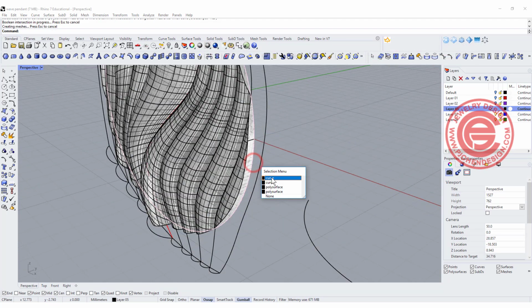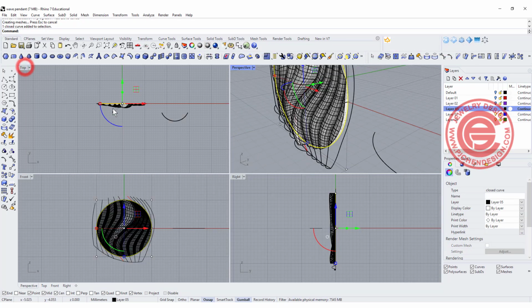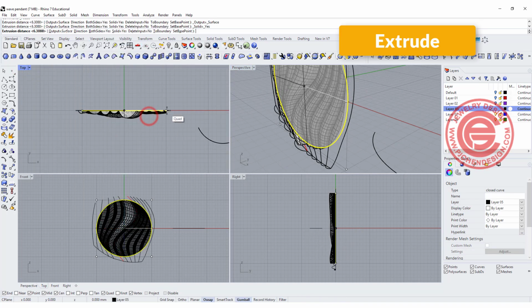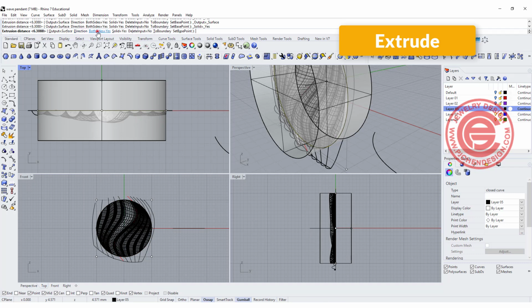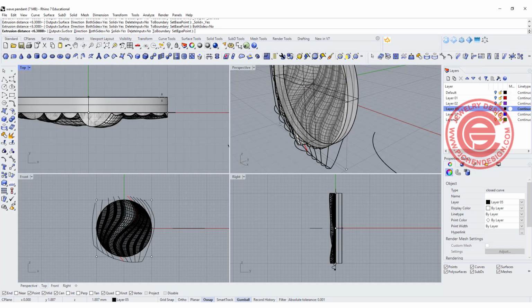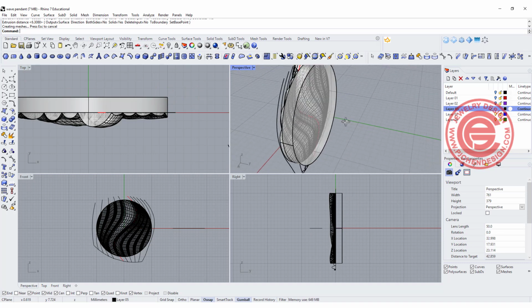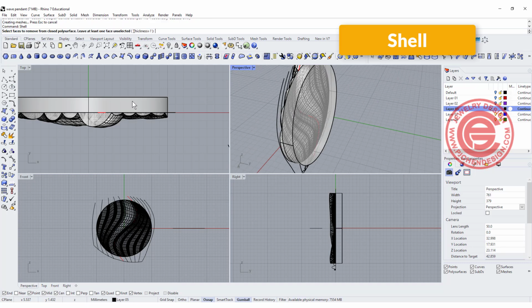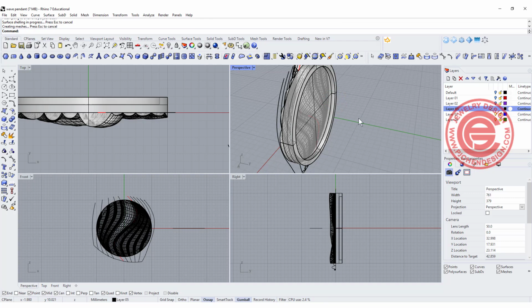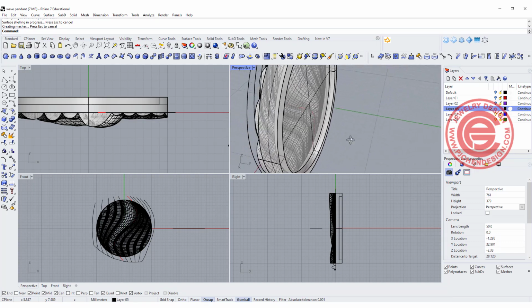And I simply want to extrude it again. So let's go ahead and extrude it straight, to whatever thickness, direction only going to one side, and maybe something like this, right? And you can make it hollow if you want to, simply using the Shell command. And then let's say I want to remove from the back 1 millimeter. So that way you will get a thickness there.